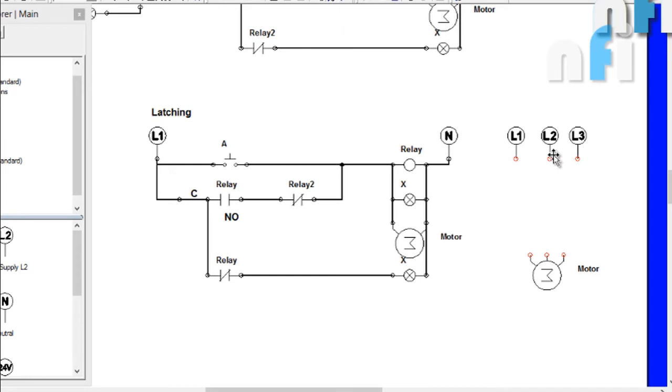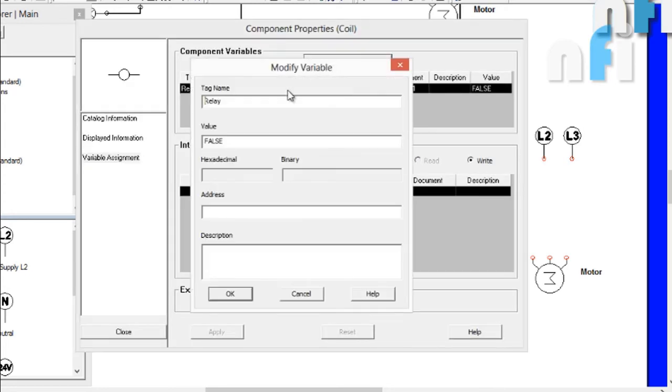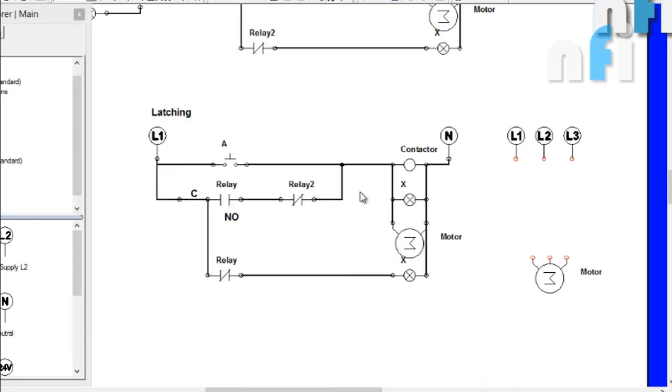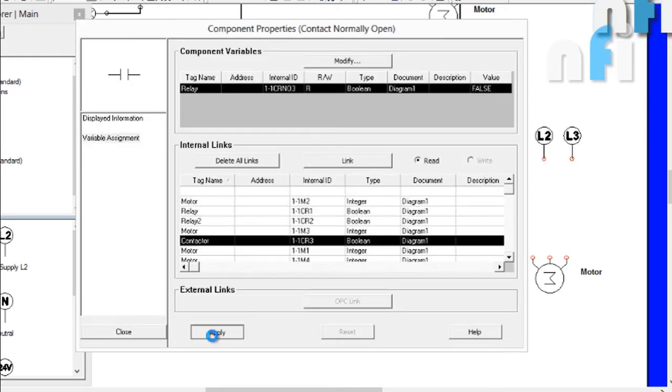And to connect these line 1, line 2 and line 3 to the motor, we need 3 more NO contacts of this coil. Alright. Now it must be noted that if you are connecting a three-phase motor, you will never use a relay. We use another device which is called a contactor. Actually both relays and contactors work on the same principle, but they are named differently because a contactor is typically used for three-phase supplies. When you need to provide three-phase supply directly to some device, we use a device called a contactor. It has the same principle.